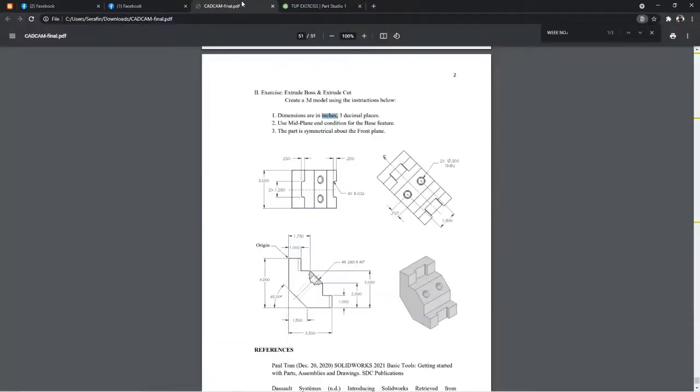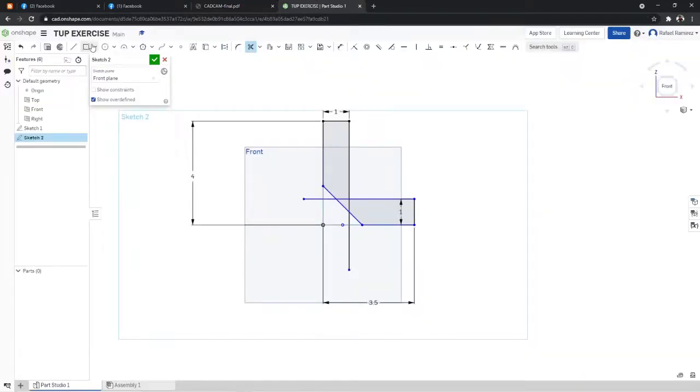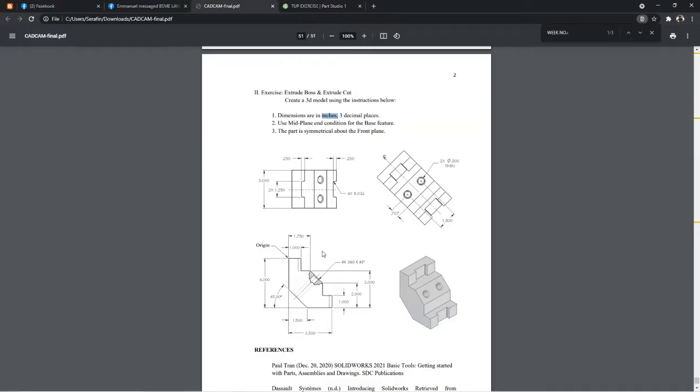So from this point, click on that, edit, put 1, click it downward, and then the next thing we would do is the distance from this point to this point is 1.75. So if we start from this point, it will be 0.75 only. And the height is 3.0. So starting from the bottom here is 3.0. That means if we start at the top, that will be 1 inch downward.